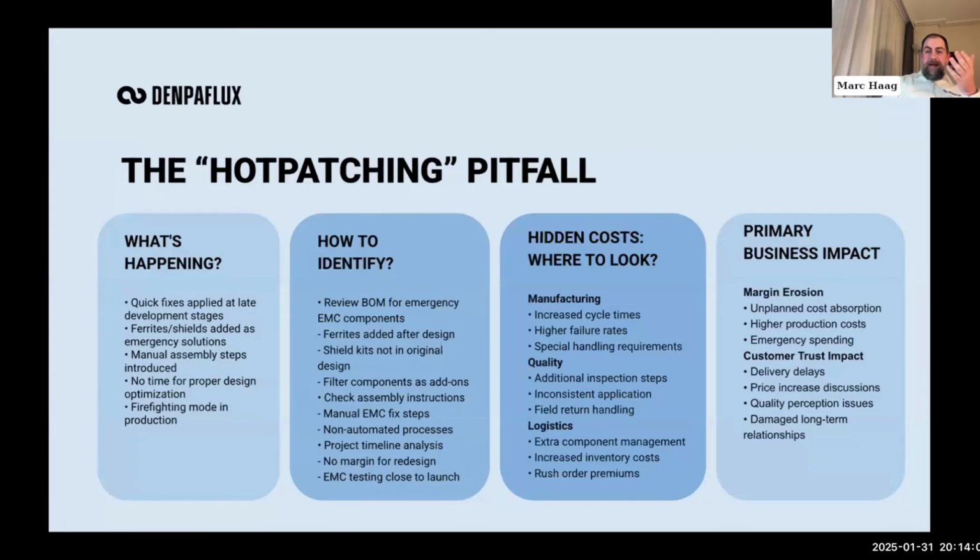Yeah, absolutely. And that is actually what is happening. You're coming back, you have some solutions to bring down the radiation by using certain materials like ferrite beads and other stuff that is around there. And, sorry if I say it this way, you're throwing it at your product to make it safe, so that you can keep the time. But sometimes that is also somehow what is expected. It is a proven technology to use certain materials to bring down your issues with EMC, EMI, and to make it work.